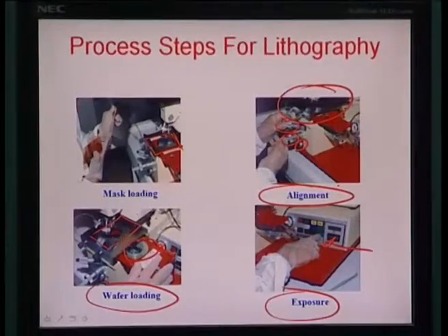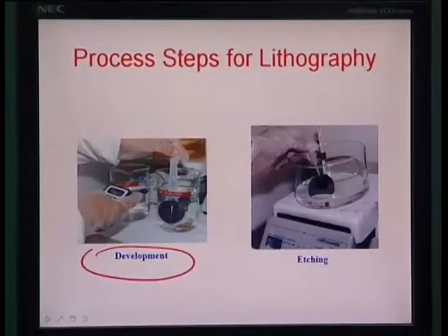So this whole thing is transported further right towards the exposure area, and there is a certain time and intensity which is preset. Intensity can be calibrated from time to time within a laboratory, and so the exposure makes the necessary changes written onto the photoresist surface, which after the post exposure bake can be developed, essentially using a tweezer to hold it, and then continuously circulating this through the developer, as you can see in this particular beaker, while a time is maintained.